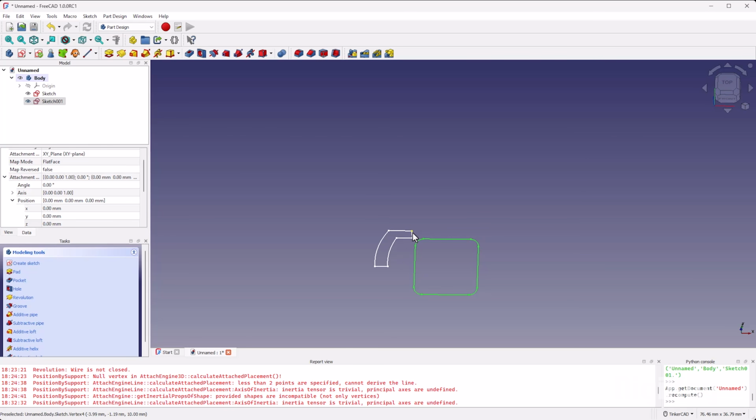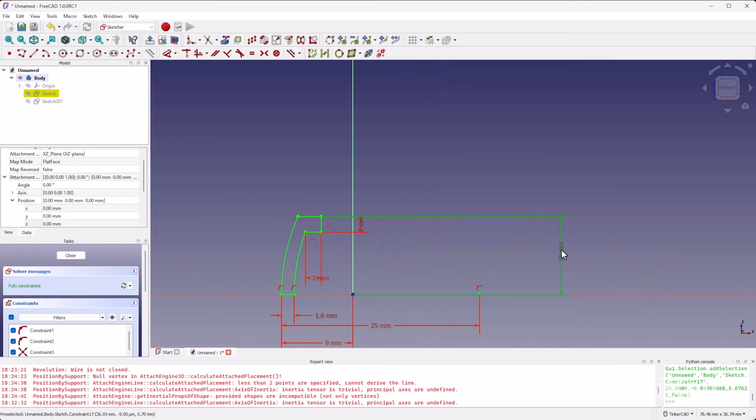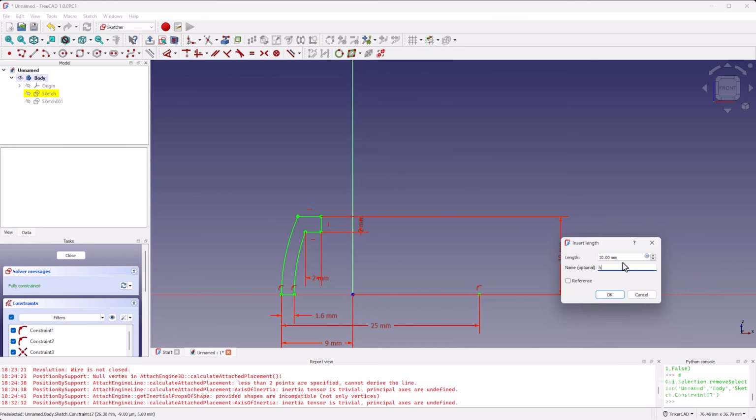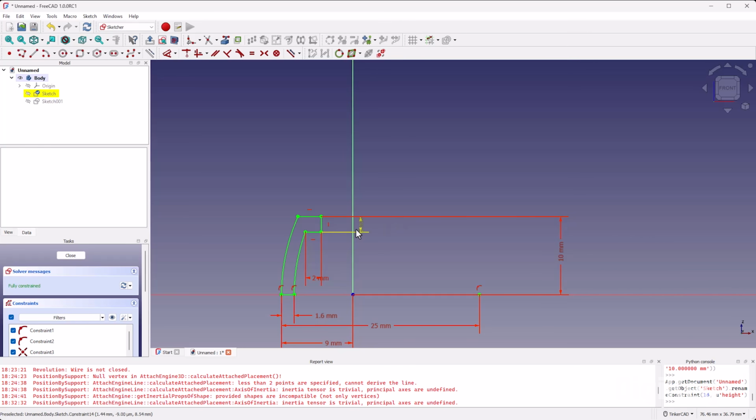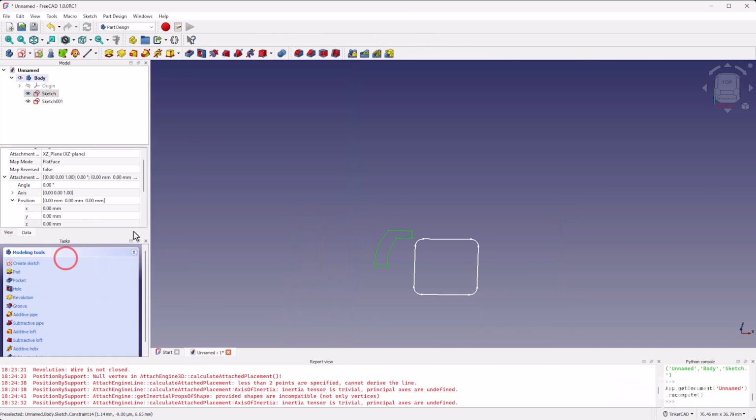That helps the tool understand we want that point to follow this path, and it will pad around it. So to do that, we actually need to name this height constraint because I like to be parametric where I can. So let's go back into the sketch where I set the 10 millimeter height here. We're going to give it the name height. And while we're at it, let's name this thickness. We're going to call this top thickness. Click close to get out of that.